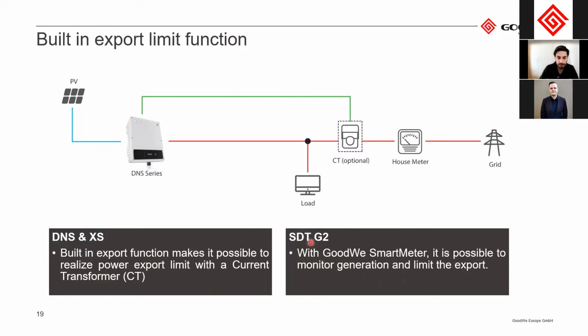In case you have the three-phase inverter, you need to have a smart meter, so not only the CTs, but basically it's the same principle. You just connect them to the inverter, and this smart meter is then connected to the CTs.